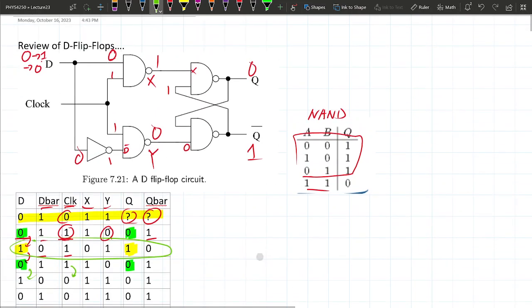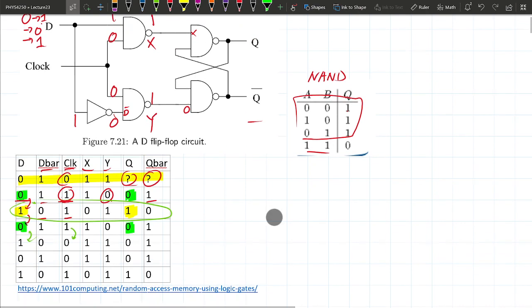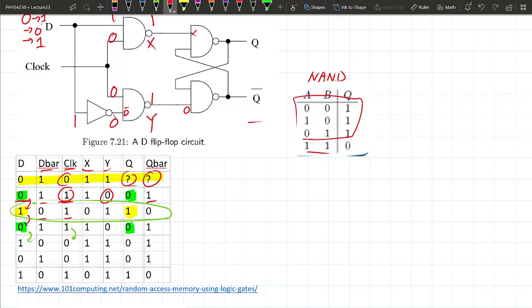So what happened is that if the clock goes from high to low, this is my third step, and I'm flipping this. This goes to 1, this goes to 1, the opposite of 1 is 0. But this time the clock is low also, okay? Therefore all of these always, oops, I erased the wrong thing. I didn't want to erase the Y, I wanted to erase the output Y. This will be a 1 as the output. This will also be a 1 as the output. And what was the initial state here before we changed anything? Q was 0, Q bar was 1.